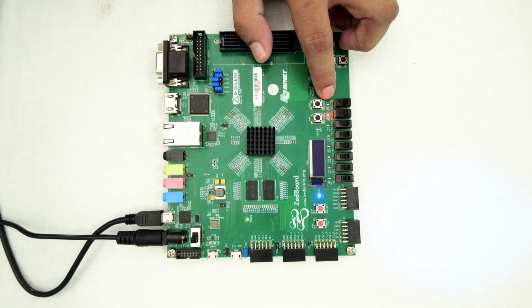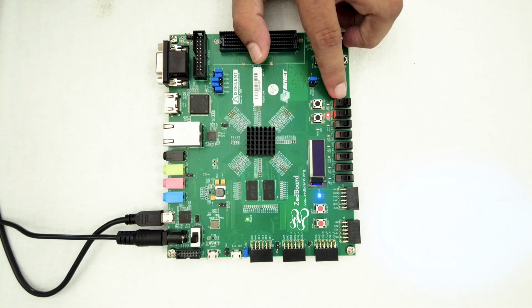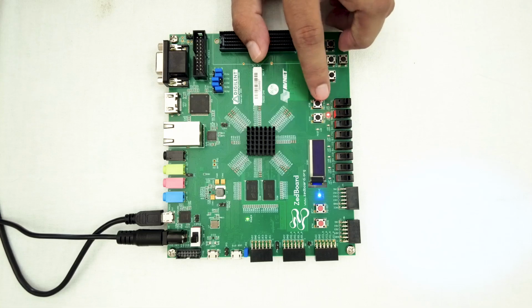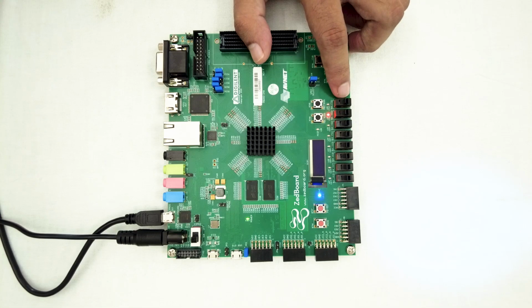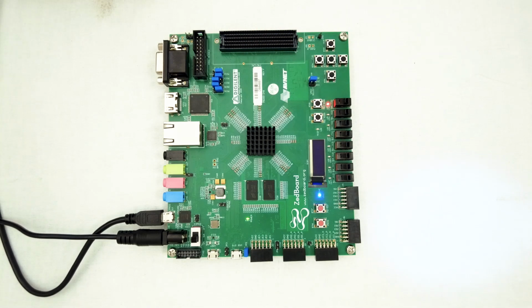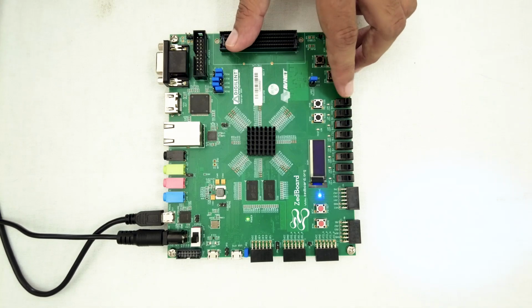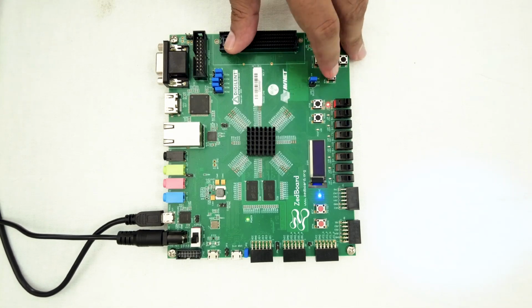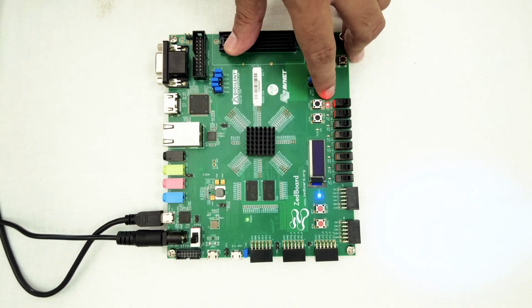And this is for clock. Again since we are giving 0, right? So in the next clock, it will be 0, 0, 0. It should not blink, right? The output should not be 1. See, again with the clock, since it is 0, 0, 0, this will turn off. You can verify its functionality by giving the sequence 1 again. It will wait for the 0, again wait for the 0. Once it detects 100, the found will be 1, otherwise it will be off. So you can verify this by using the switch, and this is the reset one. You can press this button to reset the state there, right?